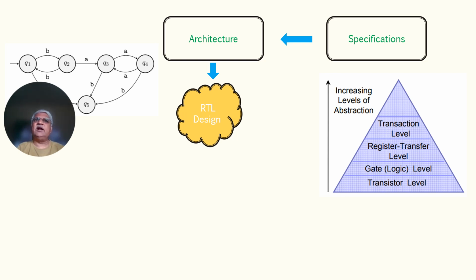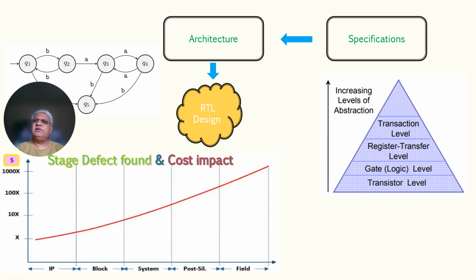Those kinds of undriven nets should be avoided. So these are simple issues which one needs to clear as part of the further RTL verification and validation process.